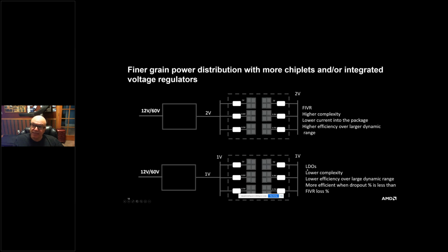power delivery scheme with LDOs, you just have to make sure your input voltage is always very close to your output voltage, right? And if, like here, you become inefficient, you become quite inefficient. But if you're only using those here on a very slow core, and you're not using a lot of them, only on the slow core, you still win. You still win significantly on power, even with the inefficiency of these VRs, with the chiplet version, with the breakout, versus, say, a single monolithic, everything at a single voltage. You can do the math and you can still win very big, okay?